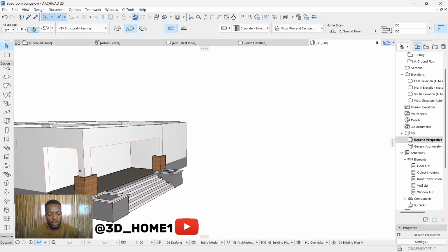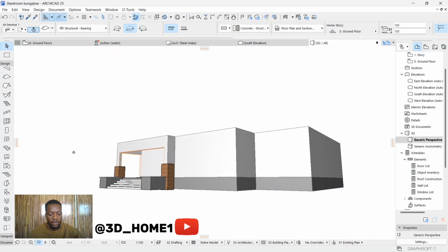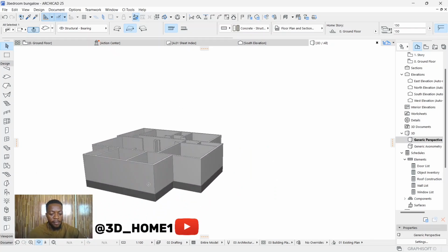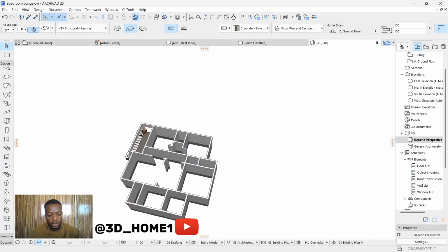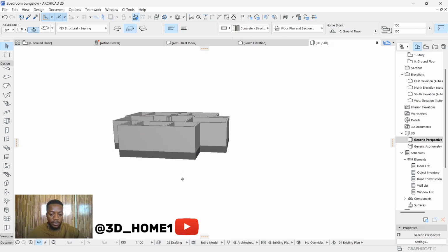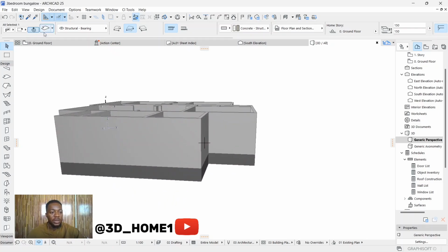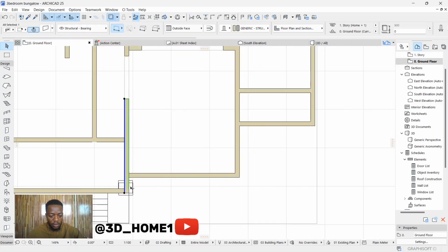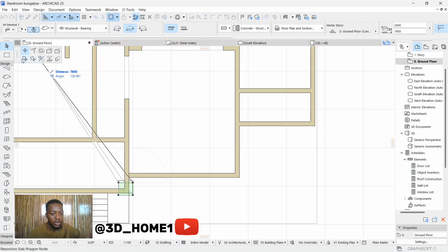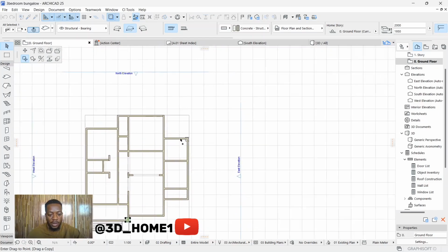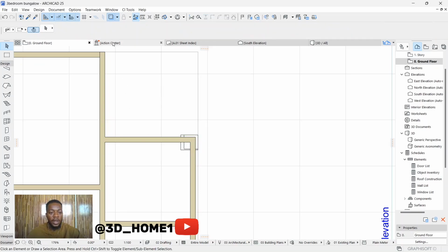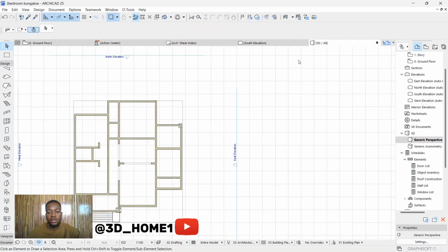Let's work on that one first. Okay, so there's an opening here. This time around I think we'll just be copying. We'll copy this column from here. Let's copy it under drag, tap control, bring it down to this point, and then let's check our 3D.